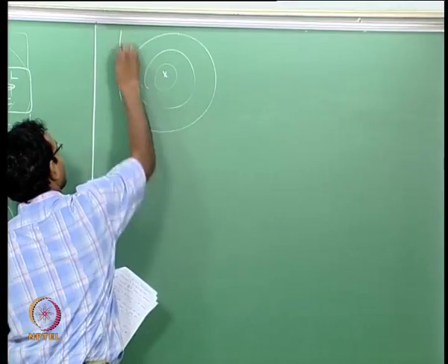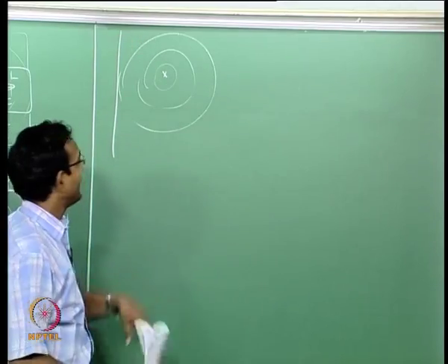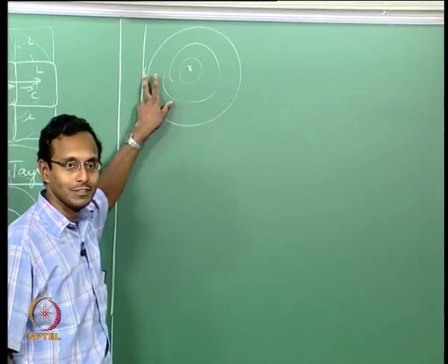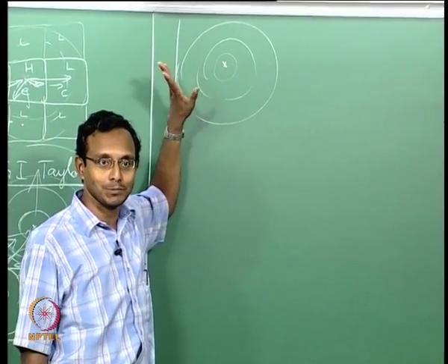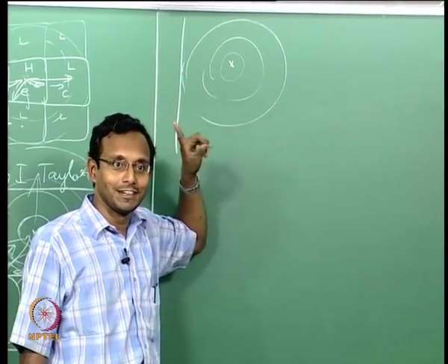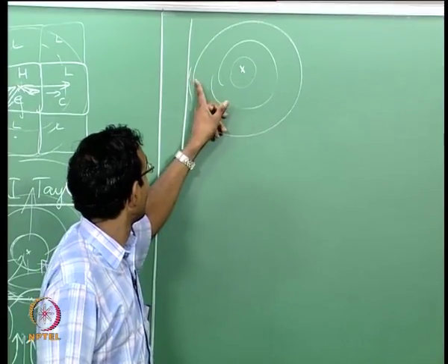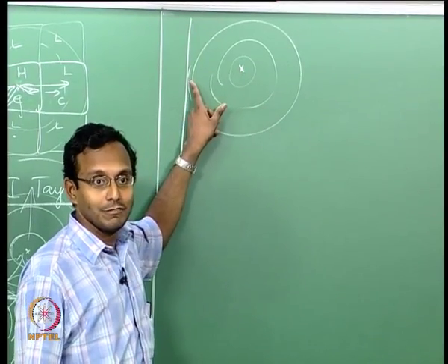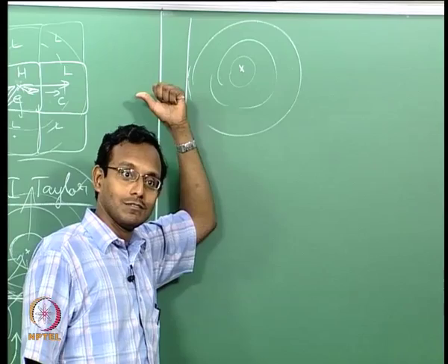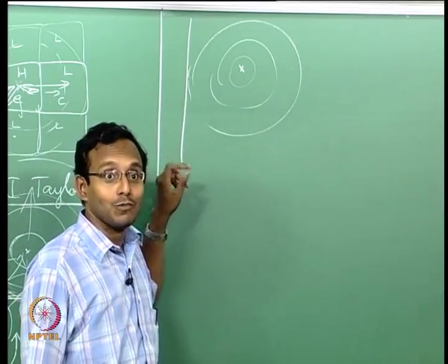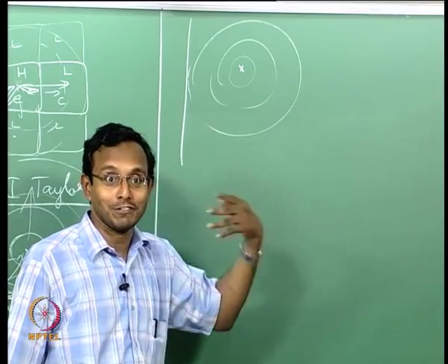If it experiences a wall on one side, then this fluid element stops there because it has finished all its job. This is the last fluid element it sees, it stops there. After that, this is the way I want to think about it. After that, there is a flow created by this wave which may be towards the wall or away from the wall, and because of the wall being there, the wall now creates new pressure waves.